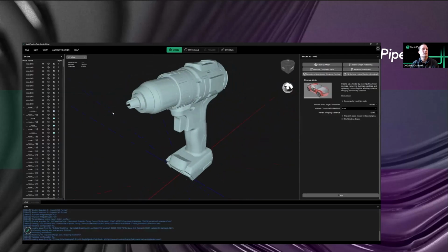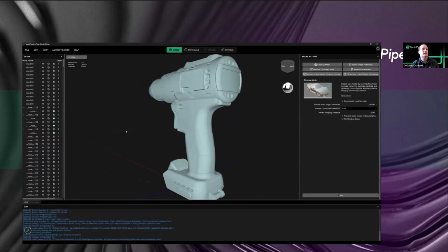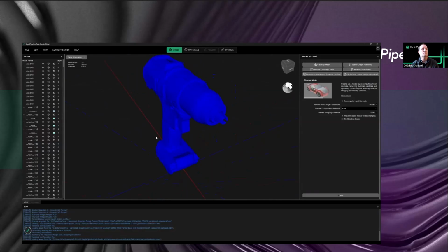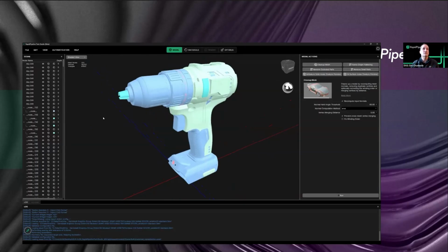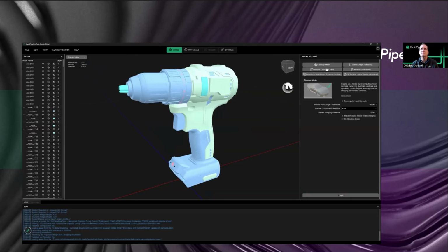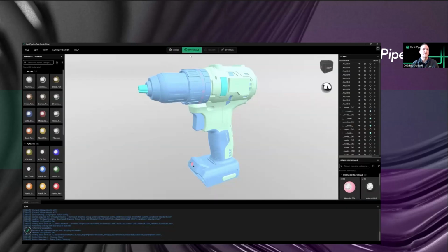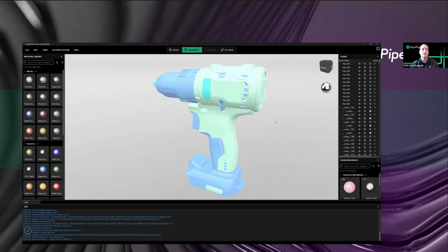And we have a UV view. So this doesn't have UVs on it. That's why it's a single color, but we can easily assign UVs here in the application. And another thing we have is face orientation. So if things are inside out, they'll show up red here. And we can talk through some of that too. We have an automated tool that fixes inside out meshes. So that's the model tab, and we have some things here for recomputing the mesh normals, simplifying the hierarchy and collapsing things. But let's dive directly into the material assignment, because I think that's cool for a lot of people.